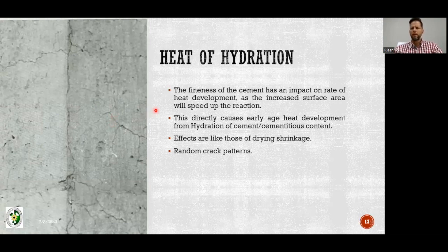And they quickly ran and found out, okay, they placed a 30 MPa concrete, and it was extended by about 11% of life, I think, at that point. But that was not enough. The concrete was just too massive, the temperatures were way too high, and they didn't take any mitigating measures into consideration when they placed this concrete. Inevitably, they rebuilt the base.